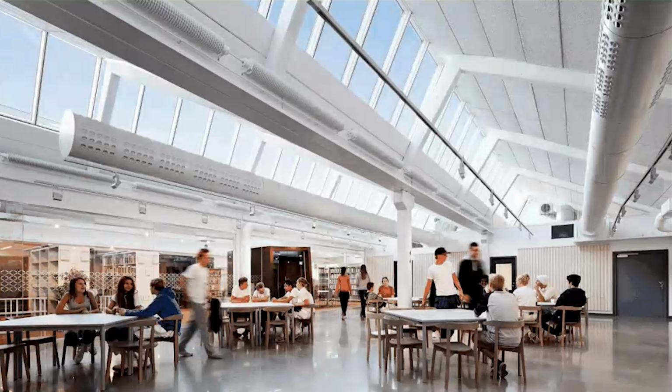So this is called a north light, and like the name suggests, you're facing the skylights towards the north. And the advantage of this with regards to solar heat gain is that you're not going to get very much direct sun. Only in the summertime in the early morning and early afternoon, you might get some low incident angle sun from the rising and setting sun. But for the most part, you're not getting a lot of solar heat gain here. So you're getting this nice even distribution of light in the space, and you don't have a lot of solar heat gain.